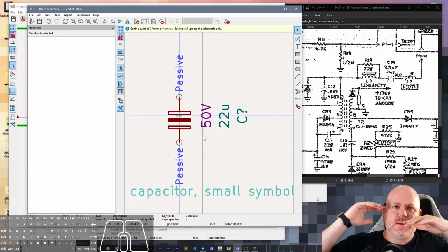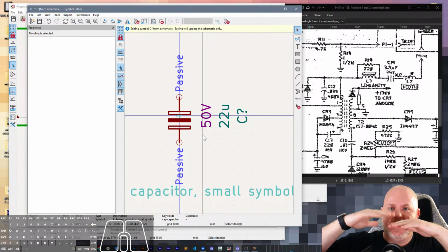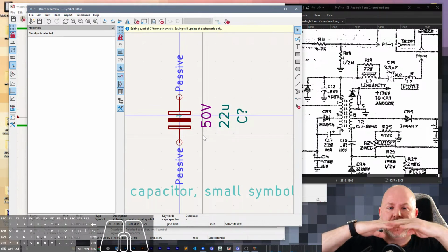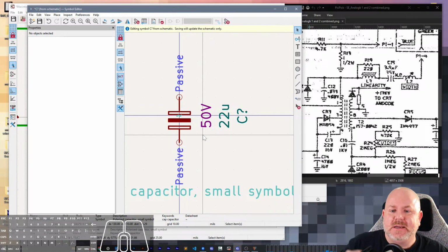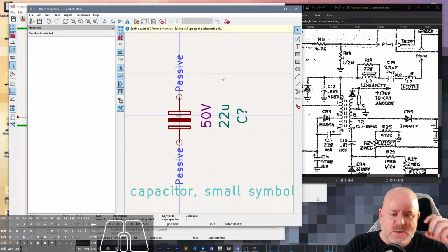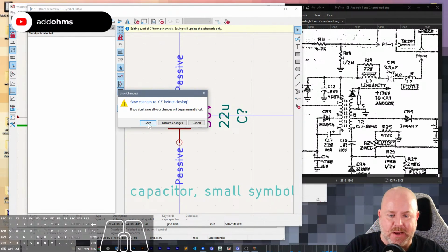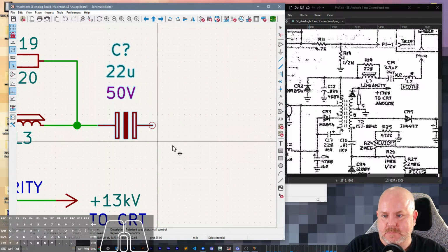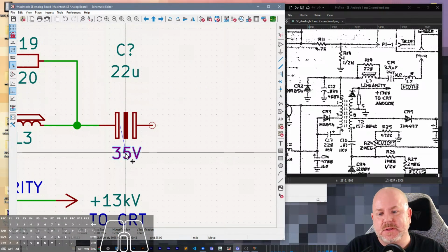In a real electrolytic can, normally the foils are either the anode or cathode, and then you roll them up. What they do is alternate, and I think every other layer, the foil has a line down the middle that literally splits it in half. So you end up with two caps technically in series with each other, and it becomes a bipolar cap. It's much more space efficient than putting two caps next to each other, but you get half the capacitance you would with a standard electrolytic. Anyway, it's a really cool thing.